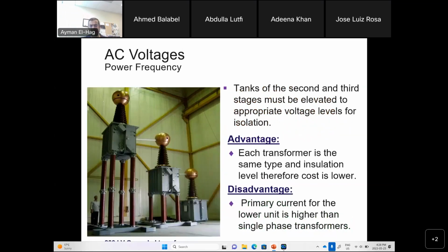So how do they look here? This is the first transformer, the first one here, and the primary will be applied here. Now, what you can see here is that the high voltage from this transformer is connected to the tank. So you are raising the voltage of the tank itself. This is why the tank has to be insulated. These are insulation. This is connected to the ground.